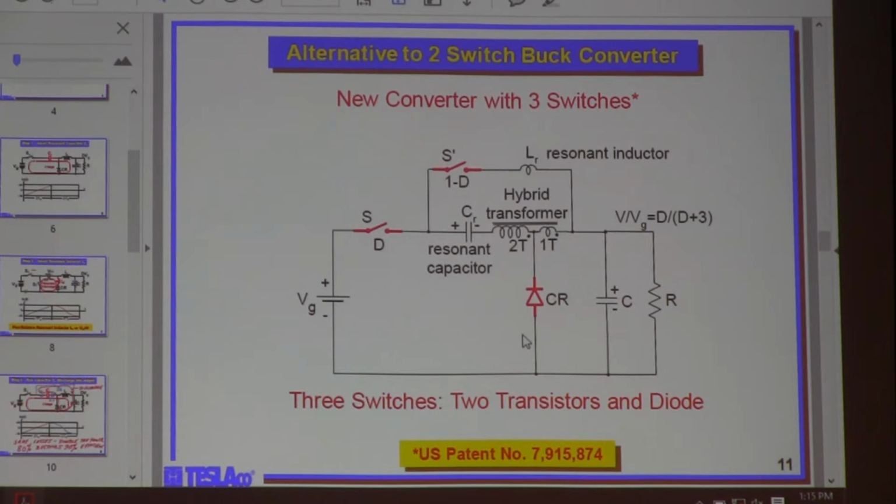This one is rated low voltage, high current. And you know what? In a buck converter, they are proposing 48 volt to 1 volt, and 48 volt has a 50 volt spike because there is hard switching. So they use a 100 volt switch on the input for 1 volt output, 100 amp. How much is that? That synchronous rectifier switch is seeing 100 volt and 100 amps. It's a 10 kilowatt switch for a 100 watt output. How does it make sense?